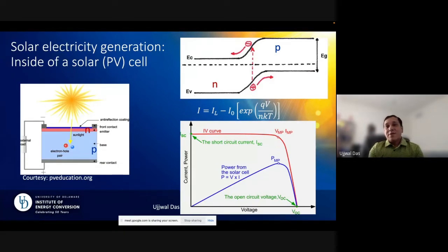So this is a PN junction diode. And when you bring a N-type semiconductor in close contact with P-type semiconductor, it forms an electric field and bends the band. So the electron can go only downwards. So once you create an electron, these electrons will separate out from where it's created and flow in other direction. And that flow of electron forms a current because as you know, you may have studied that dq/dt is the current.